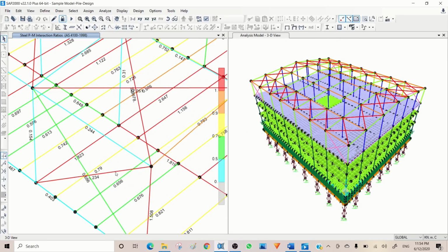For very strong bracing, for heavy industrial structure, we're going for a UC section or a very strong welded plate section, I shape, with thick flanges and thick web. But here a simple double angle or double C section would be okay. I will leave it as it is. I don't want to go through trial and error and finalize our design. I'm just showing you guys what needs to be done.